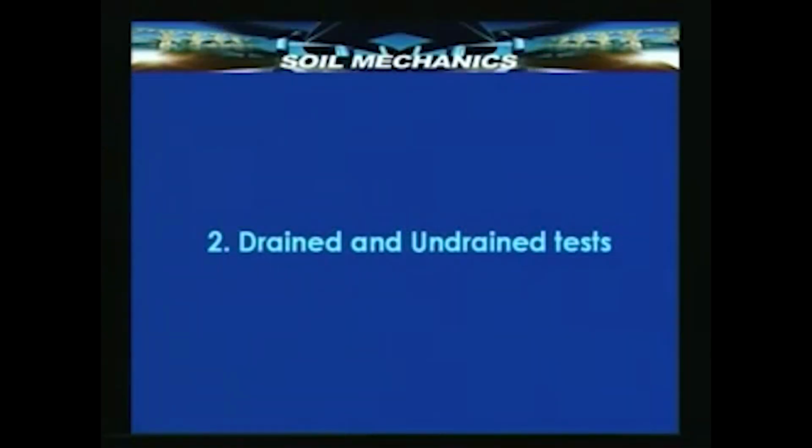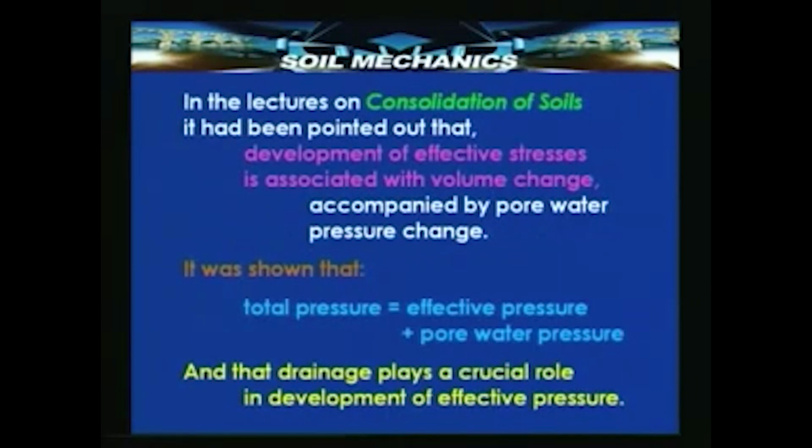And therefore, it is very important to know what is the condition with respect to drainage in a typical shear strength test. Let us see the next slide, drained and undrained tests. In my earlier lectures, I have told that development of effective stresses is associated with volume change and by pore water pressure change.